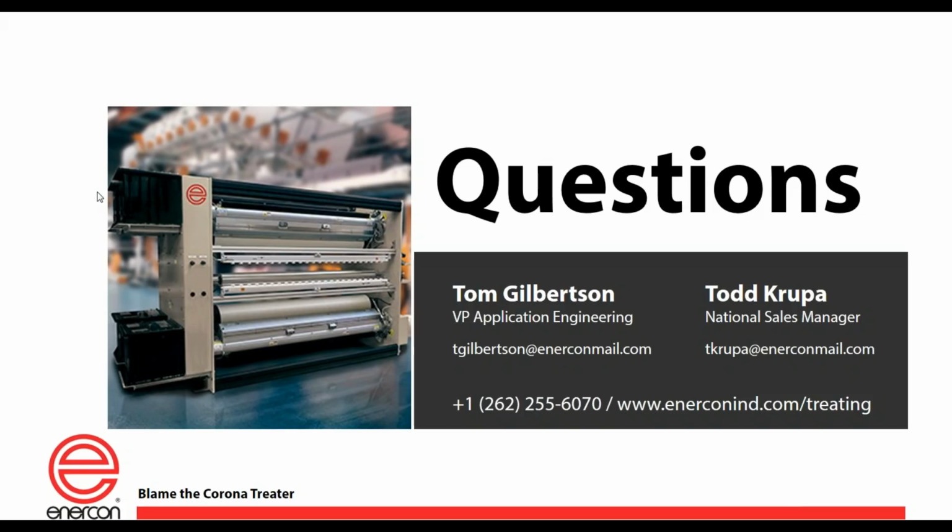I've got a question. To improve the lamination, they use primer combined with corona treatment. Is that common? Oh yeah, it is common. On extrusion coating machines, for example, it's very common. You unwind, you go through a primer station, you go through a corona treater, and you go into the extrudate. It's very, very common.